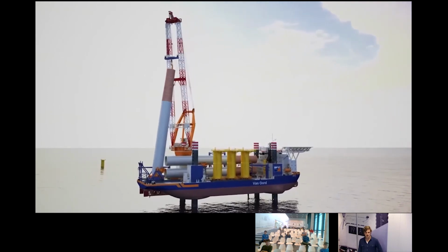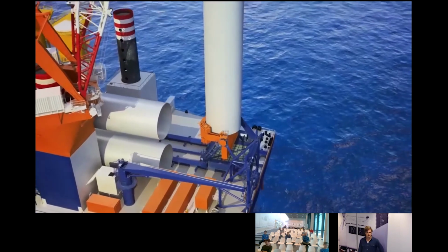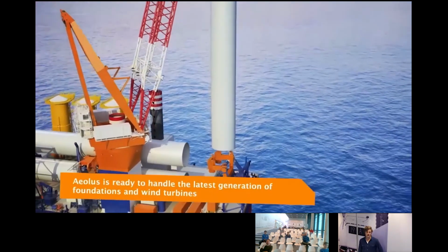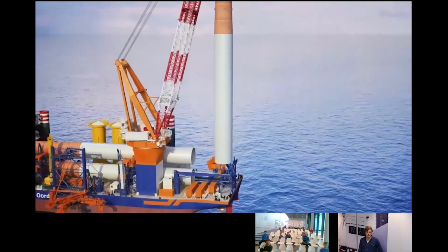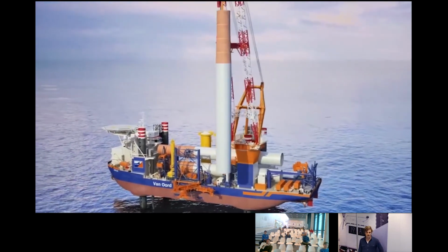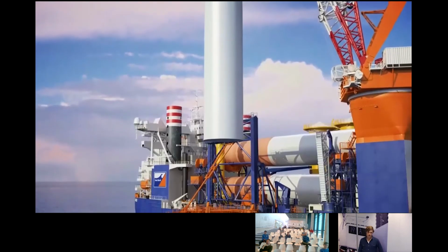The crane is also of high capacity. I'm not sure, probably this capacity is around 2,000 tons, but also this number is increasing in the future vessels. So the monopile is now upended with some similar upending hinge, and then accordingly it's placed into the gripper.